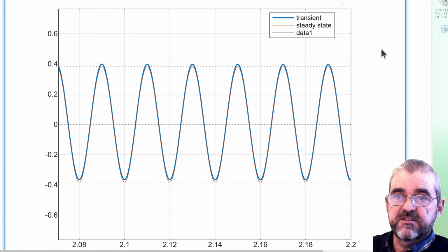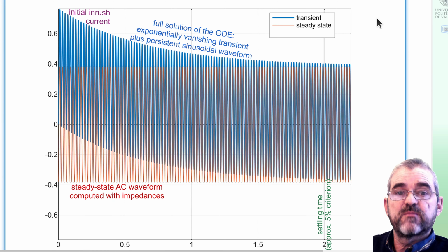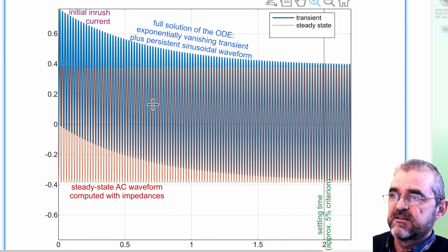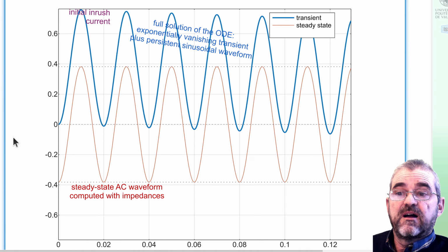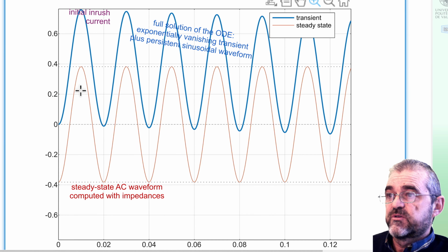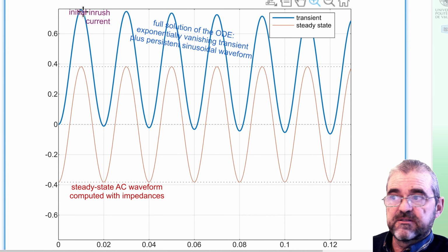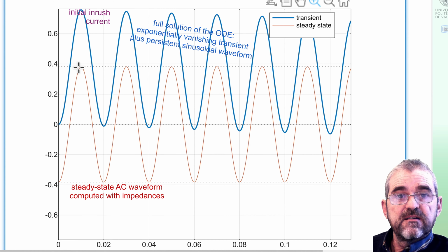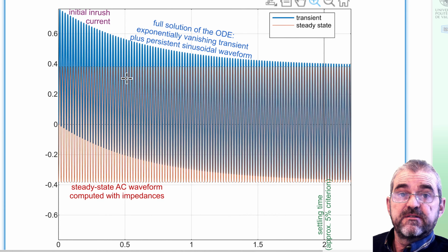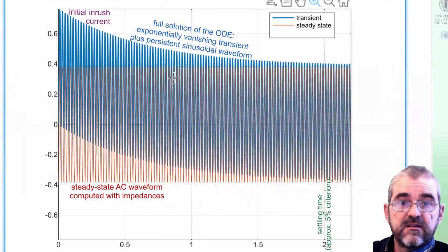Of course, for a mathematician, it will take an infinite amount of time to get there, but for us, 2 seconds is close enough to be within component tolerances. And as we see in the first stages, our inductor current is displaced up so that the peak inrush current is double that of the steady state AC computations. If this inrush current is a severe problem, we may have a trick for avoiding it.